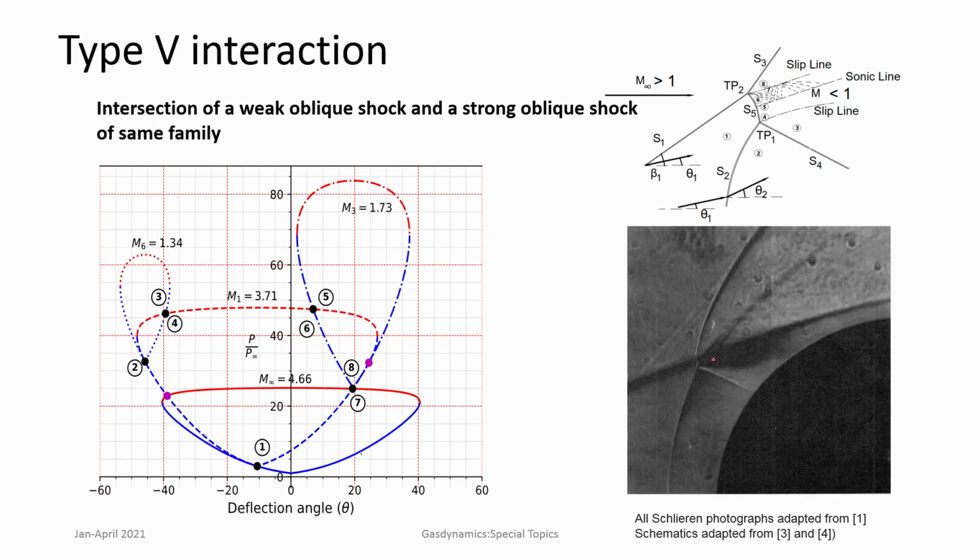Here in this region you have the two shocks, and you have the region containing the jet, and the slip line is smudged in this case, but essentially it is just the shock wave that interacts with the body, and the corresponding shock polars can be drawn, and we can understand shock interactions very well with shock polars. So this is one application where shock polars can be used to a good extent.